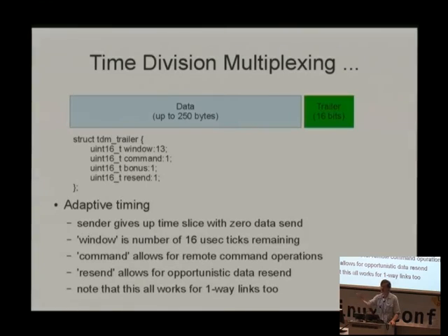So we can actually get quite a lot of data through reliably if most of the data is coming in one direction. But as soon as there's data that needs to upload, you're uploading a mission, a set of waypoints or some control information or a new set of parameters, and you've got a flood of data coming upstream, it immediately adapts towards that and can shift towards mostly being the ground station transmitting and switch back immediately to mostly the plane transmitting. And it costs you about 15%.